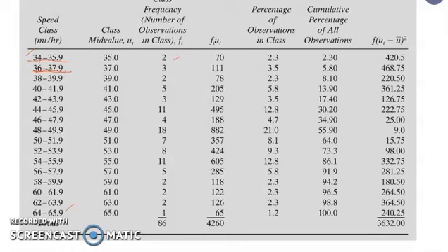Then you go up to the end, then you sum up. That is the summation, which is 86. Which means 86 is the total number of cars. If it does not tally to 86, there is an error, so you have to go back again. It must tally to the number of cars.